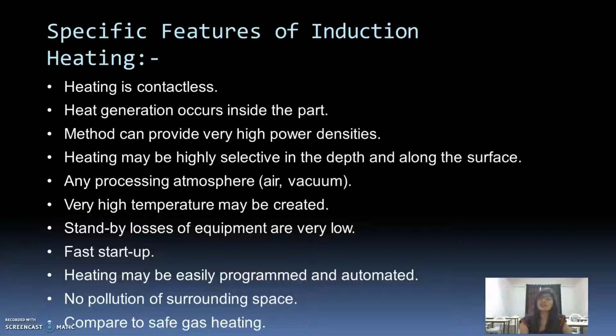Now, specific features of induction heating. In induction heating, heating is contactless. There is no direct contact with the object or material to be heated. The heat generated occurs inside the part. Heat generated does not go outside, or heat dissipation does not take place in the induction heating method. The method can provide very high power densities. Heating may be highly selective in depth and along the surface.